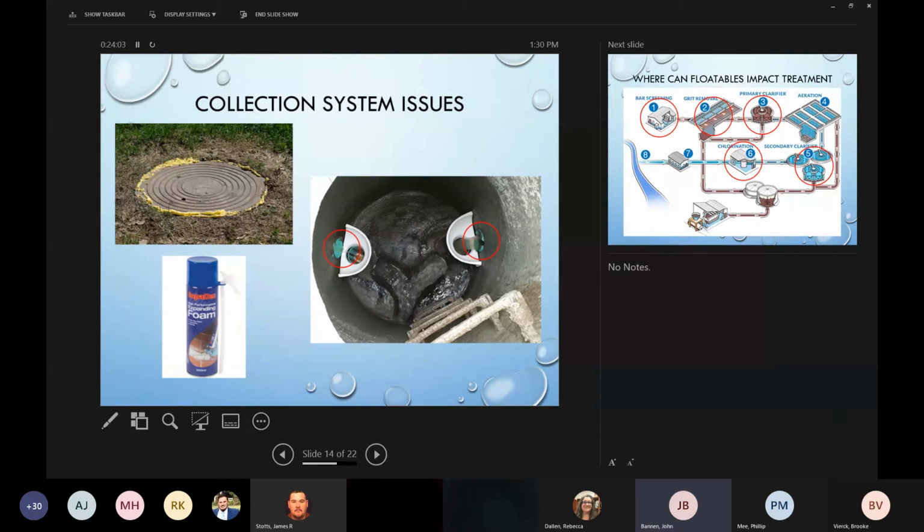And secondly, on the right, what you see here is where lateral lines protrude into the manhole structure. What you see here is correctly done. These laterals are grouted in with a cement-based grouting and a cement-based product as they protrude into the manhole. I have seen spray foam used to center and to grout in pipes.